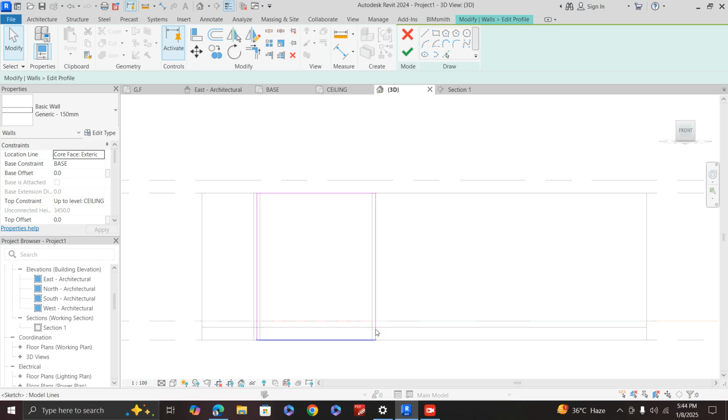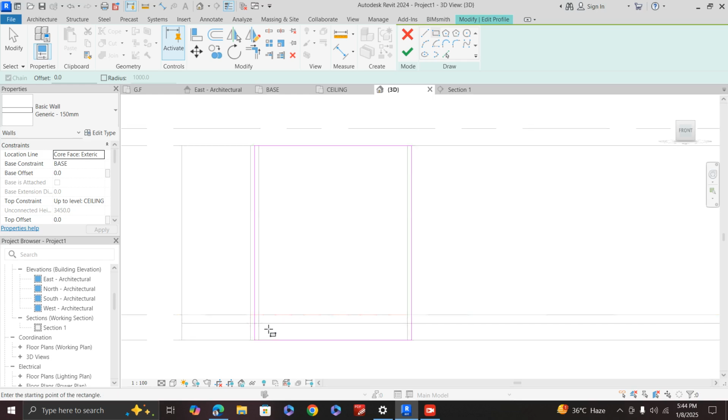So basically this red outline is indicating the area of the current wall. So whatever openings you create using maybe a rectangle or anything is going to create exactly that hole on that wall. So we want to reduce this wall height now. We are going to reduce it from the base here. We want to reduce it down to the top.